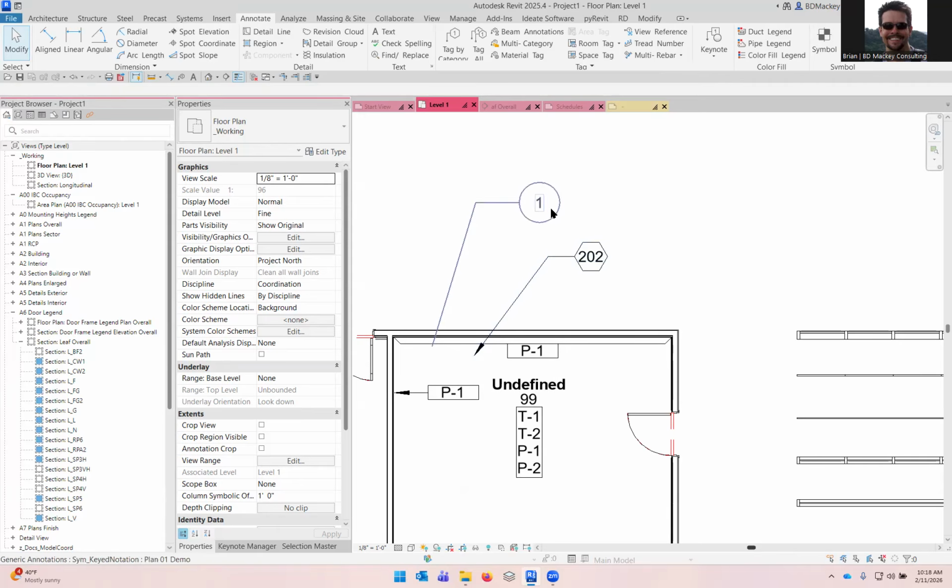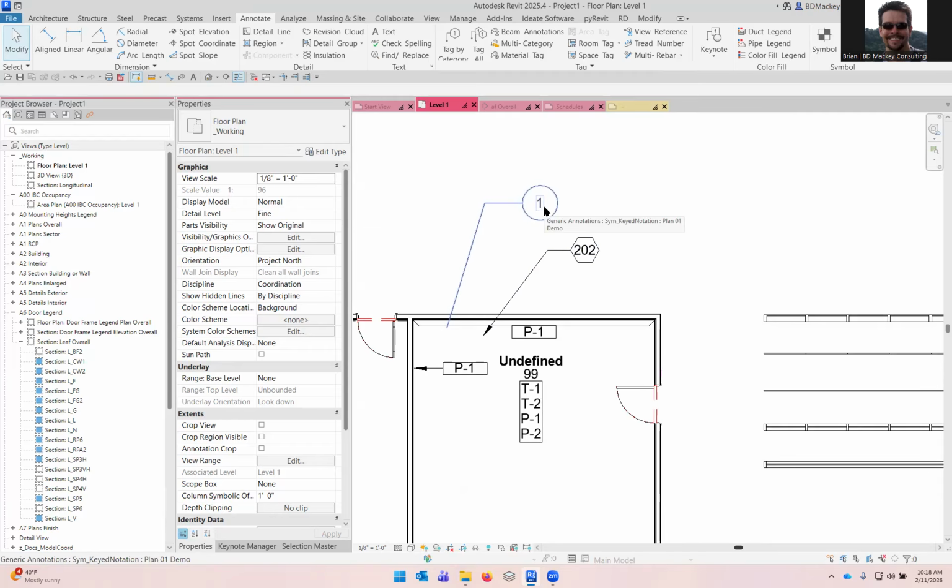And again, these are more specific sheet notes or plan notes or elevation notes. If you still have your overall general notes, like, hey, dimensions are always to face of stud, blah, blah, blah, those are still going to be, in my mind, a legend that you put on there. An additional thing regardless of either of those, it's going to be a schedule I put onto the sheet. It's a real schedule and not a dumb legend where you manually try to match it, AutoCAD style.